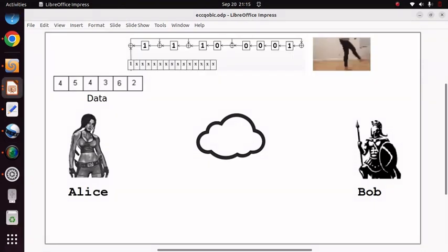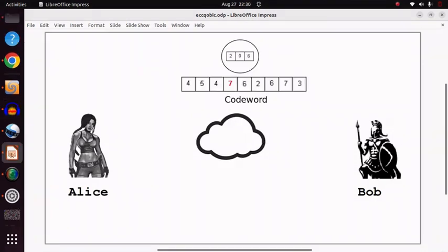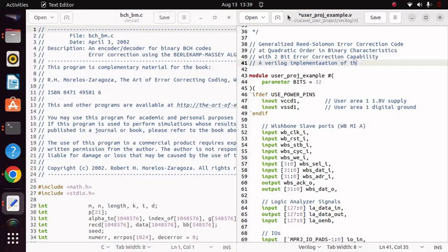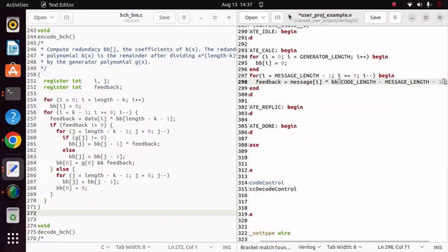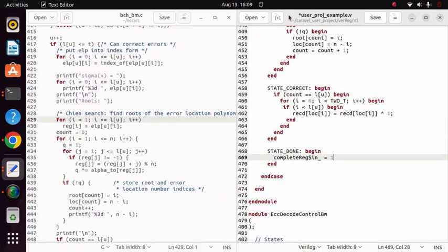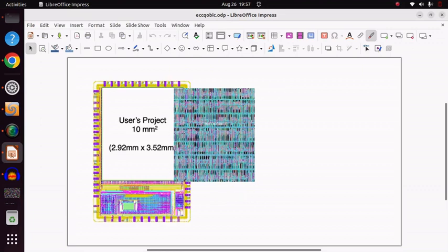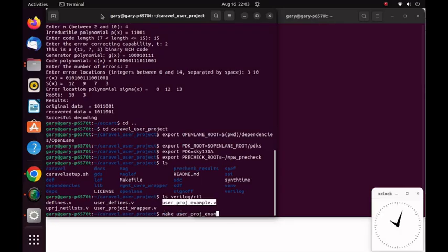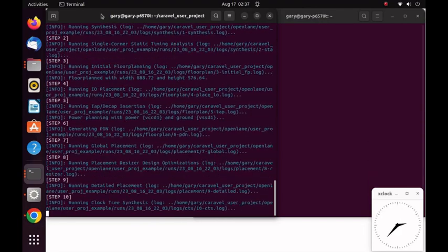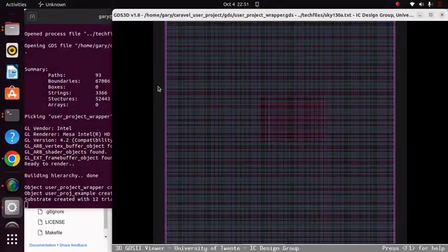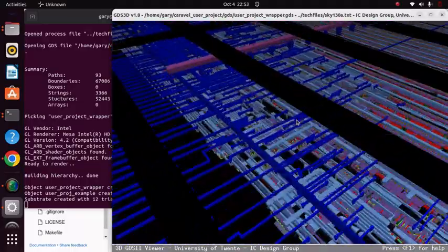To deal with noise in communication, error correction coding can be used. Hardware realization of the ECC circuit is implemented by transcribing C to Verilog for the sake of minimum effort. The Verilog circuit can be synthesized into a physical layout on the Caravel SoC platform, synthesizing and hardening the circuit into GDS layout. The various layers of masks can be visualized in 3 dimensions in the GDS 3D app.